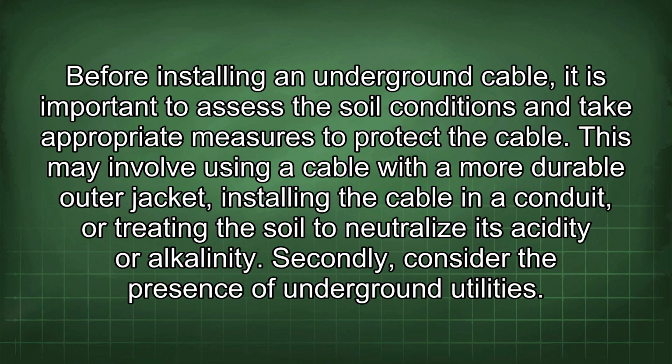Before installing an underground cable, it is important to assess the soil conditions and take appropriate measures to protect the cable. This may involve using a cable with a more durable outer jacket, installing the cable in a conduit, or treating the soil to neutralize its acidity or alkalinity.